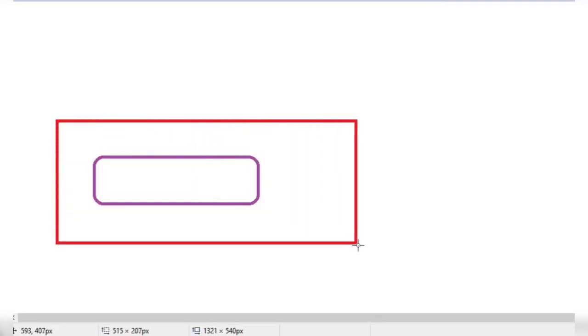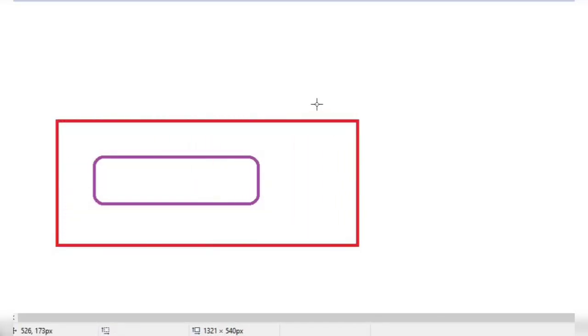Now let's understand with an example. Suppose this is a heater that is high risk. Before breaching the system, we have to set up the high risk FME boundary with a high risk signage FME zone that will be red in color. The FME monitor will be adjacent to this boundary.